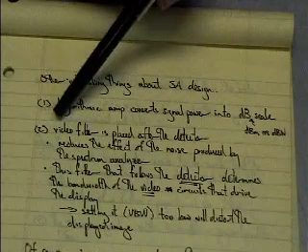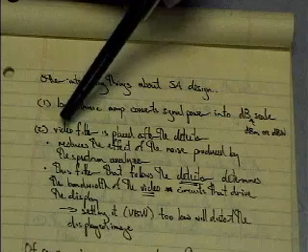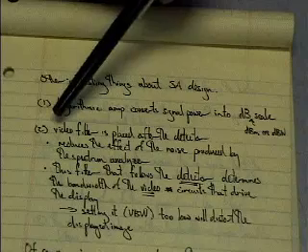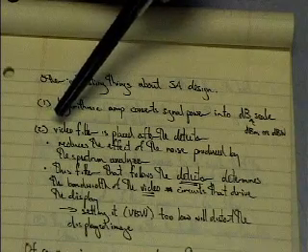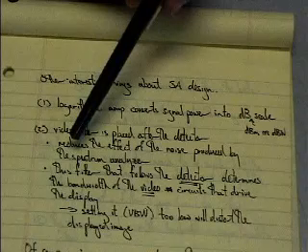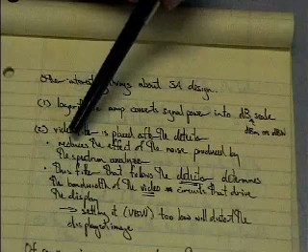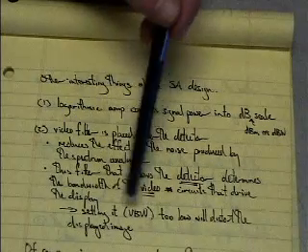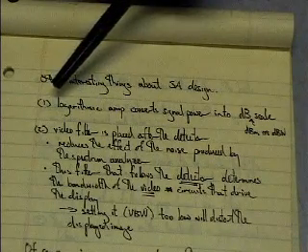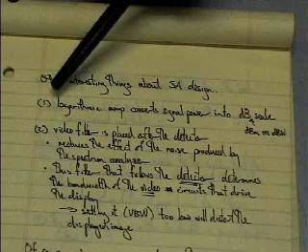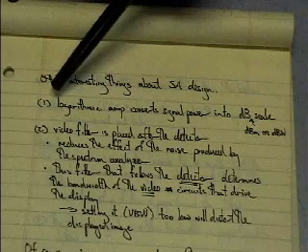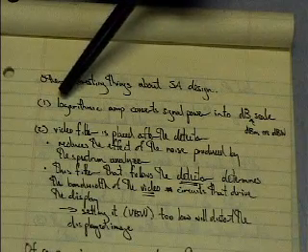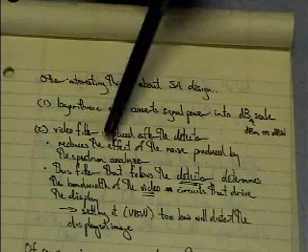In addition, at the output of the power detector is a video filter, and the video filter is used to reduce the noise effects that the spectrum analyzer itself is producing. And so you can play around with this, the video bandwidth filter, or the VBW, to clean up your picture. It turns out the spectrum analyzers we have, this is kind of a hidden feature. You really have to poke around on it. It's not as evident as it is on some units.